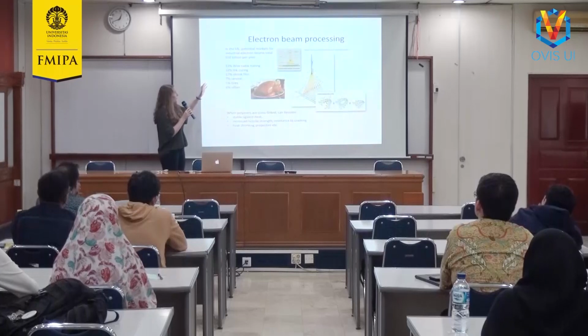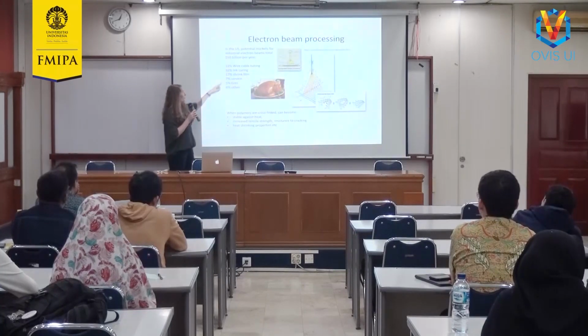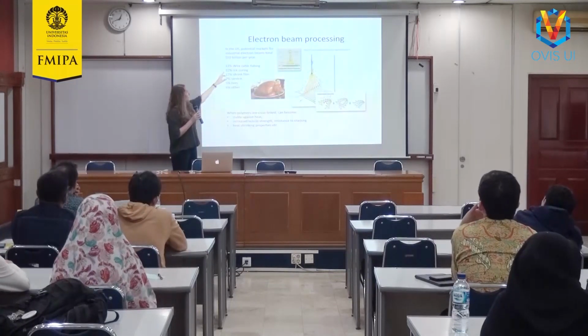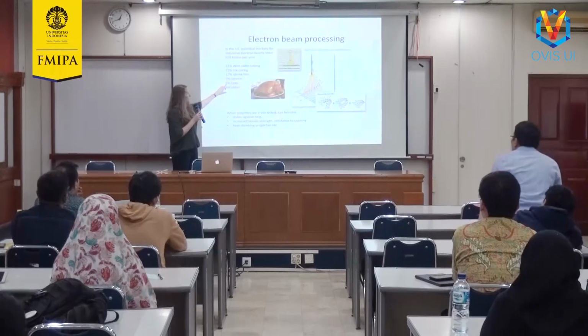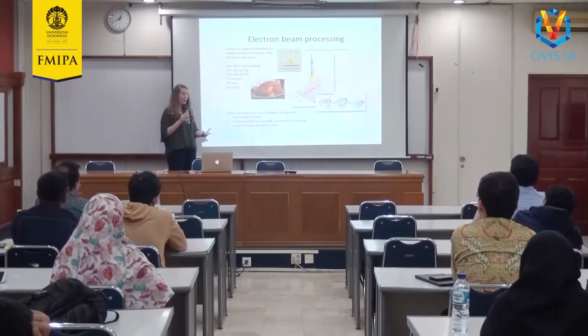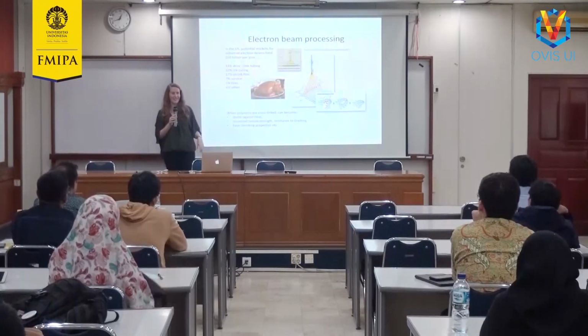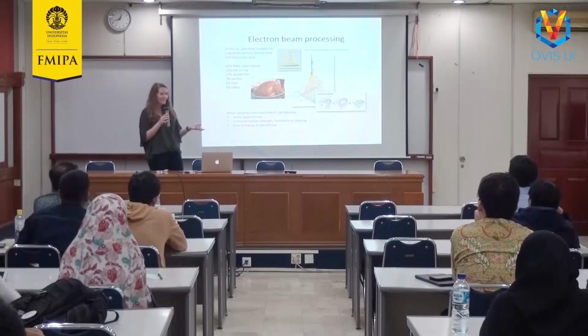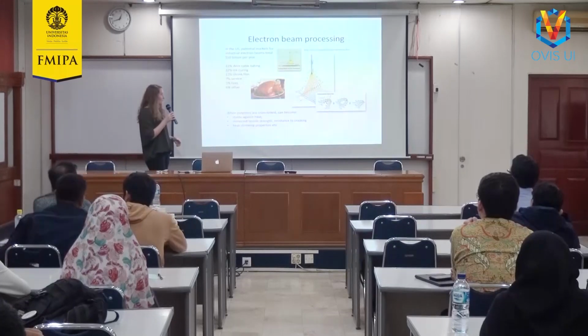In the US alone, something like $50 billion worth of products get treated with electron beam processing. So it's everything from wire, the tubing that goes around the cables and wires, to curing ink on printed material, making shrink film, automatic shrinking films, making car tires strong, and all kinds of other things. This turkey is there because the shrink wrap around turkeys in the US is treated with electrons so that it shrinks properly and stays strong.